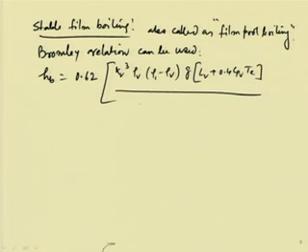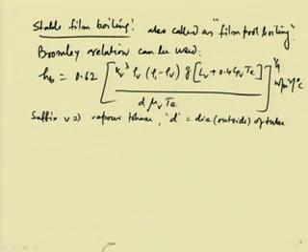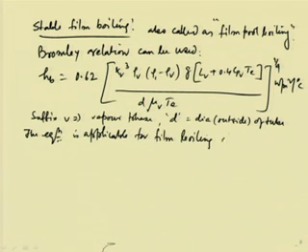temperature, divided by d, the diameter of the tube, and this is for a horizontal tube, into mu V into Te whole to the power 1 by 4, and watt per meter square per degree centigrade is the boiling heat transfer coefficient, where suffix V implies vapor phase, okay, and d is the outside diameter of the tube, okay, and the equation is applicable for film boiling outside horizontal tubes, okay,